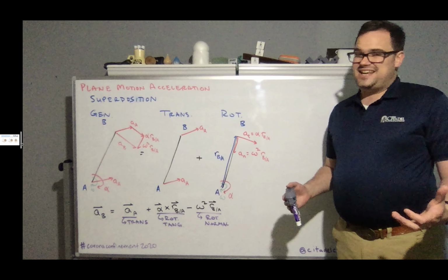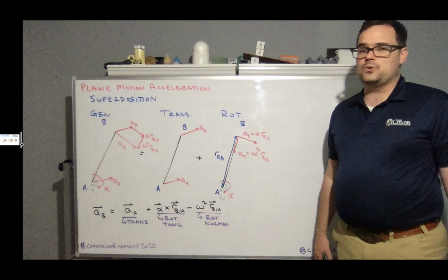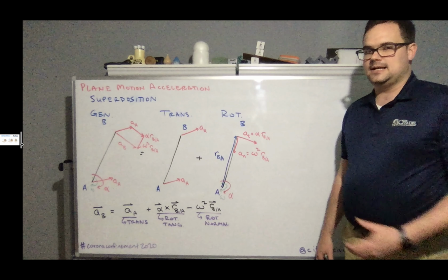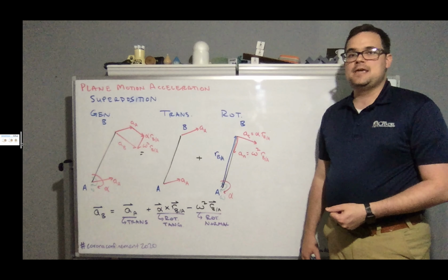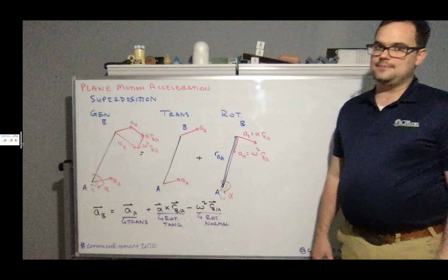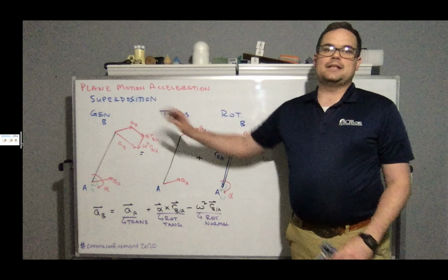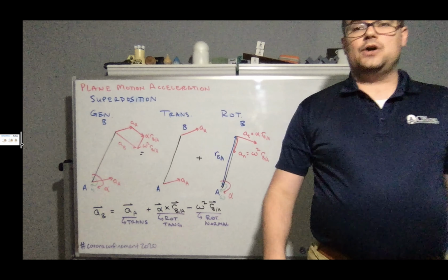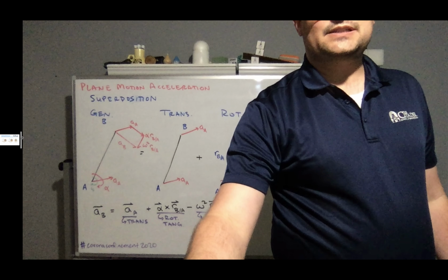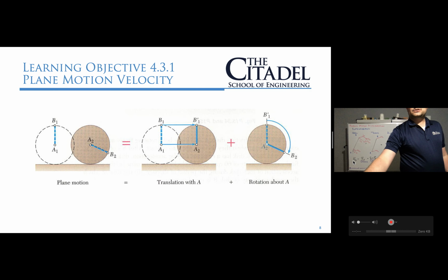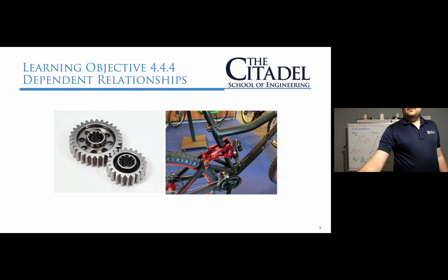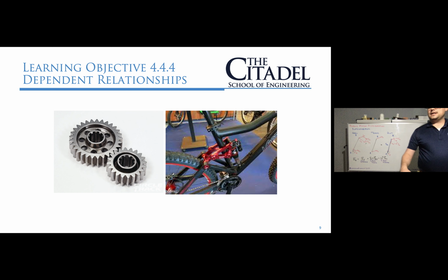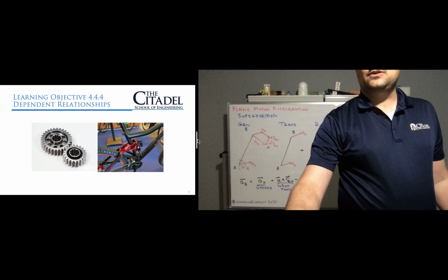There is no instantaneous center of rotation equivalent for acceleration, which is unfortunate because this is going to be fairly time consuming. You always have to draw 3 diagrams. You always have to collect up and write the equations for each point. Now, that said, we also want to talk about dependent motion for acceleration. And so if we look at our slideshow here, we'll remember that we talked about gears and contact surfaces. And when we talked about our contact surfaces for these dependent motion equations,